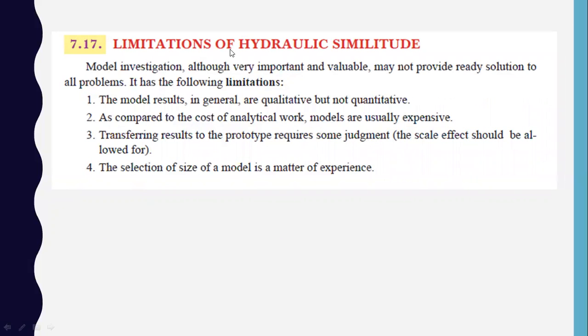Limitations of the hydraulic similitude. Model investigation, although very important and valuable, may not provide a ready solution to all problems. It has the following limitations. The model results in general are qualitative but not quantitative. Second, as compared to the cost of analytical work, models are usually expensive. Third, transferring results to the prototype requires some judgment. The scale effect should be allowed for. Fourth, the selection of the size of a model is a matter of experience. So without experience, you cannot do these things.